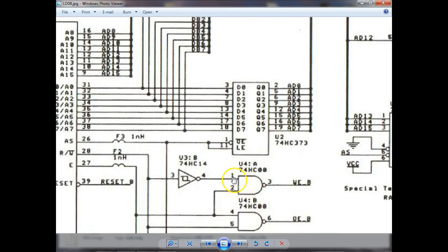So you see, one of the first things they do when they design these things is they assign the pin. And you can see this is U47 and this right here, I'm sorry. So normally this is U4, U4A, and U4B. You know what they're doing, but look, this one uses pins 1, 2, and 3. This is the exact same IC, but it's using pins what? 4, 5, and 6. So they get the same U number.